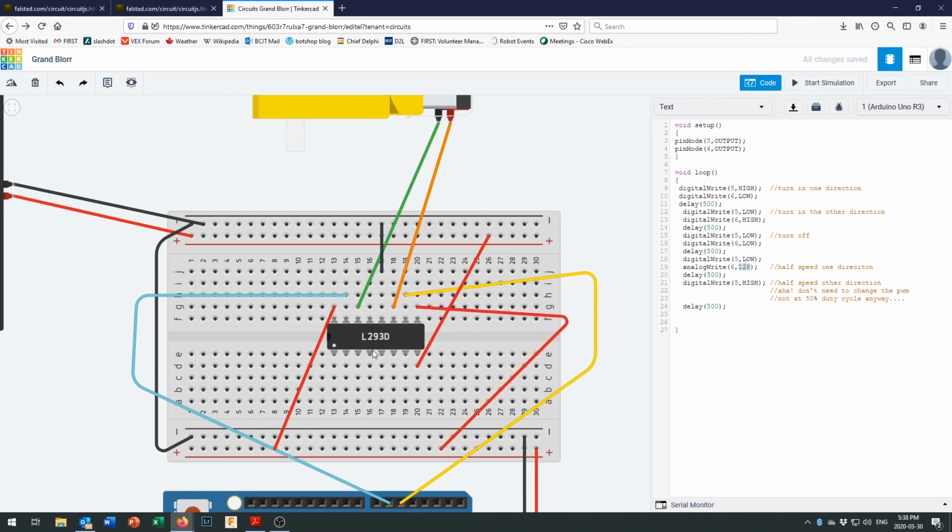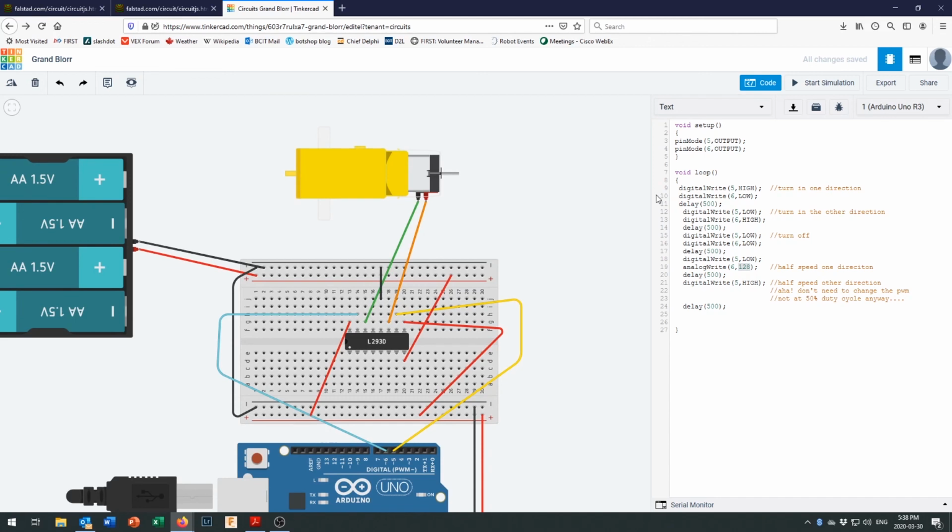These are all electrically connected inside, and the main reason we've got 4 ground pins on here is actually for heat dissipation. The chip uses those pins to get some of the heat out of the chip. And so once again, here we go. We can start that simulation. And we've got the motor spinning forwards and backwards. So you could add another motor right in here, and you could have the 2 motors controlled, and that would be exactly the same as the BoomBot that we showed you in the second slide.